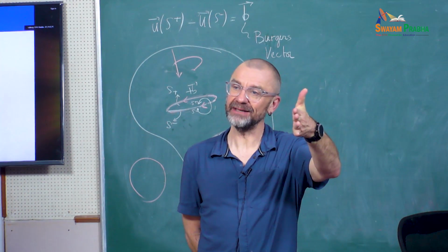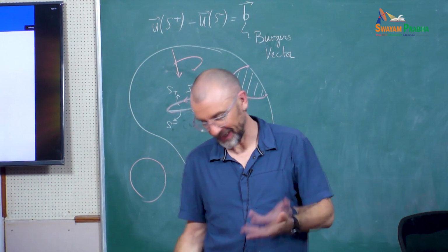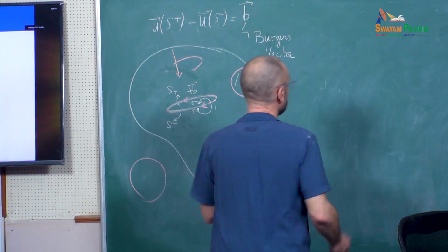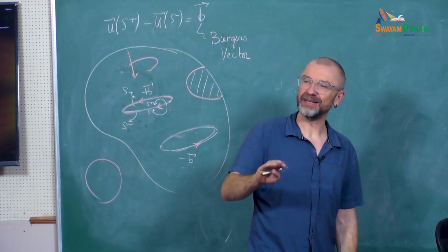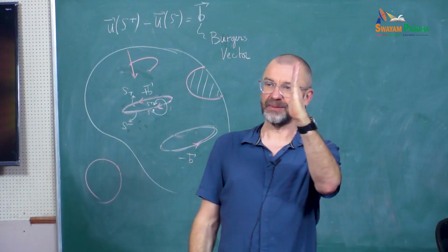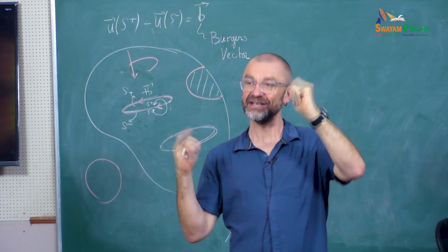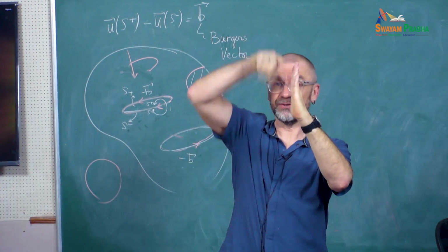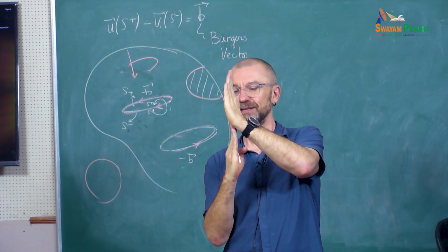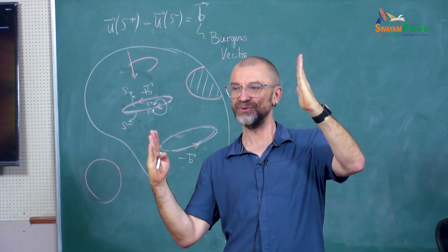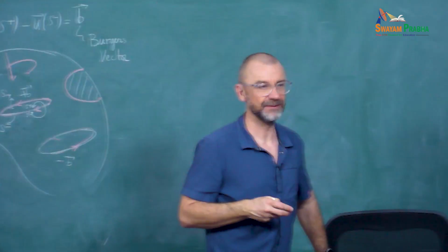So you mean the extra plane, the extra half plane? Yeah. Okay, I can answer that now, and then we'll go. You have an extra plane here, but actually you have an extra plane on the other side too. So the extra half plane, you have one extra half plane on top here if you do the shear, and then you have one extra half plane at the bottom. So it means that your initial plane here has been cut in two halves. I'll show you an illustration later on. If it's not clear, ask the question again.